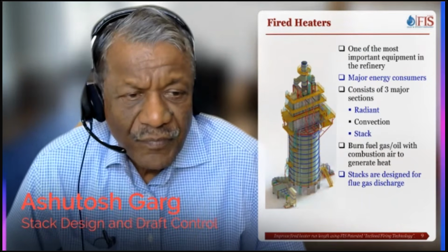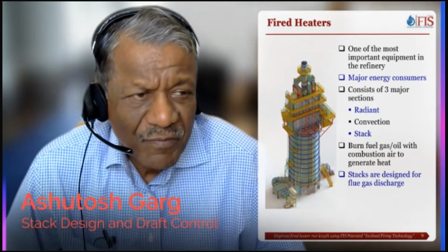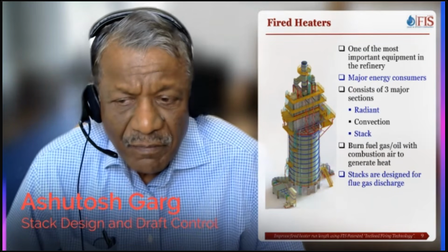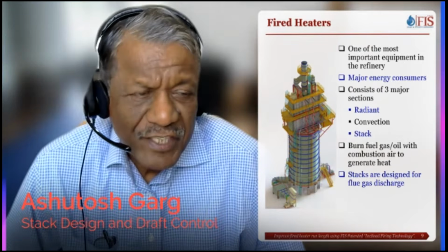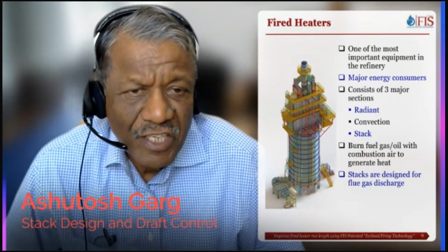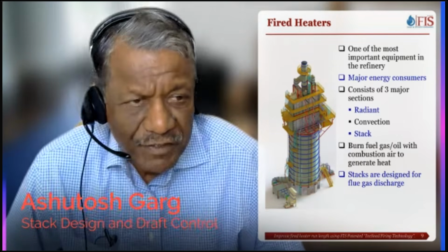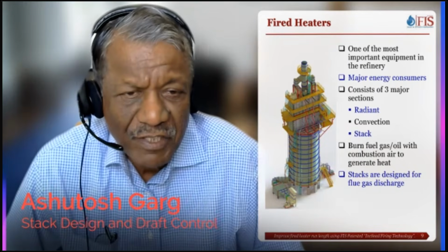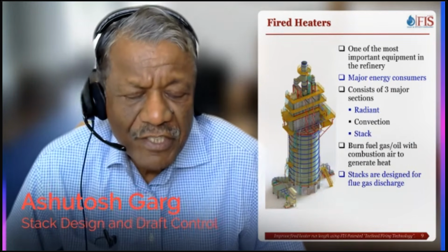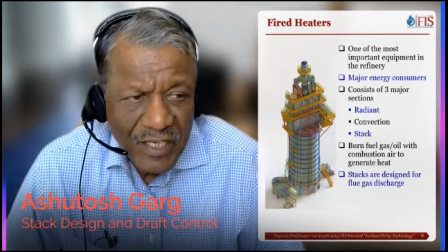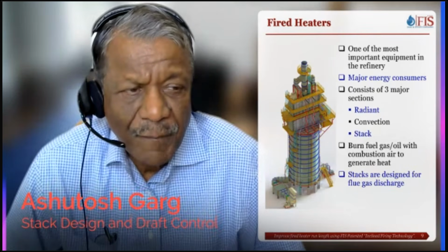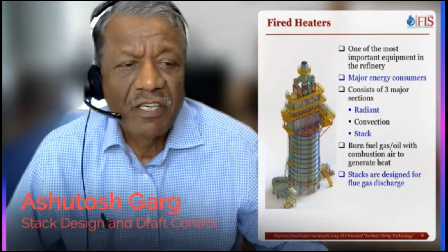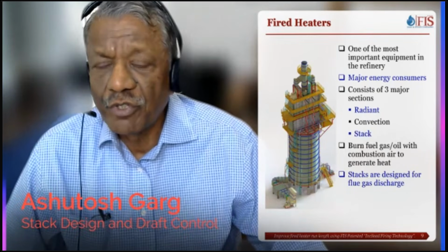We burn mostly fuel gas these days, but there are still some clients who burn fuel oil, and they burn it with combustion air to generate heat. That heat is transferred to the process to preheat the charge, whether it's for crude service or vacuum service. The flue gases, which are products of combustion, are vented to the atmosphere through the stack. That's basically how fired heater construction is. I'm sure you all know that.